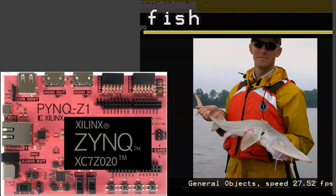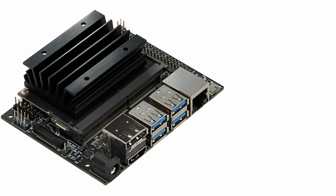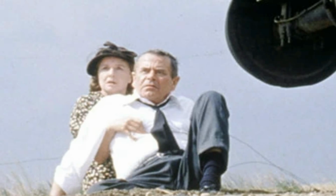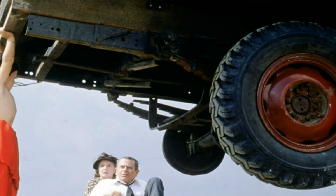On the other hand, Jetson Nano, an embedded GPU chipboard, has 512 gigaflops of computational resources. Our design achieves similar AI performance to Jetson Nano using only 45 gigaflops of resources. This means that we achieve similar performance with less than a tenth of the resources. This proves that this hardware design is very efficient compared to existing designs.